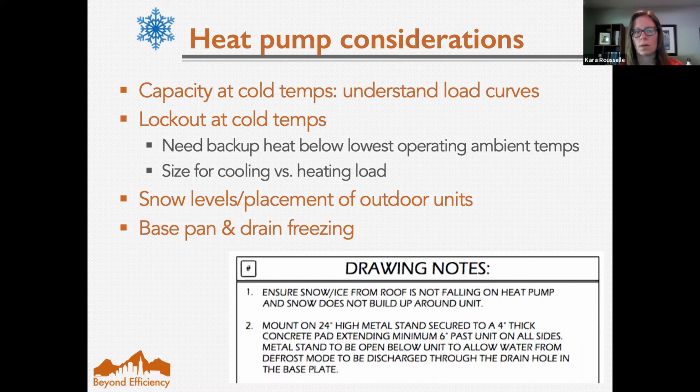Yeah, it depends on the equipment, on what they tell you. Each manufacturer will tell you something a little bit different, but I would not plan on having any heating past, depending on Mitsubishi Minisplits, I think say -13, they're working on going lower. Air to water heat pumps is usually around -5 to -8.